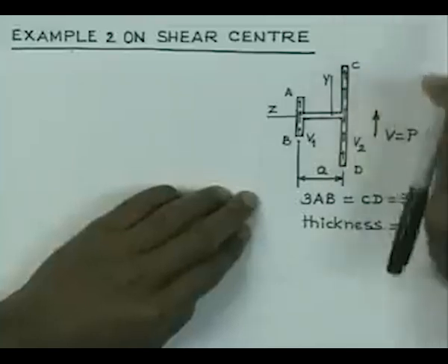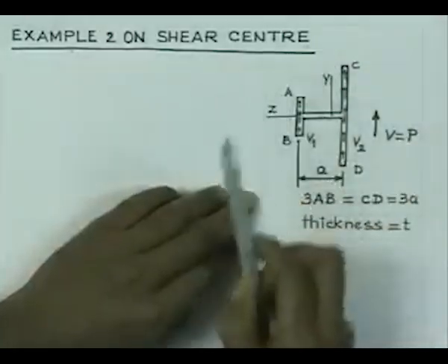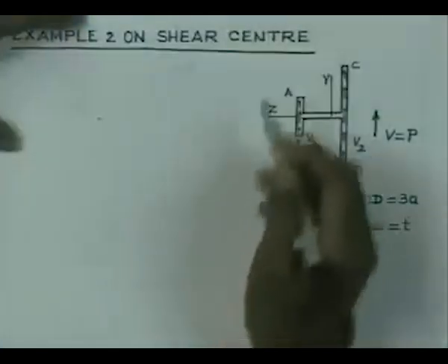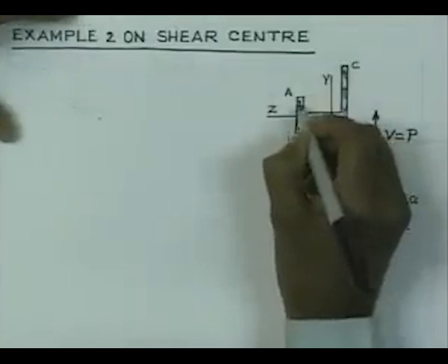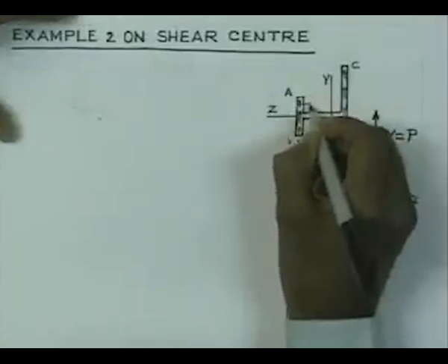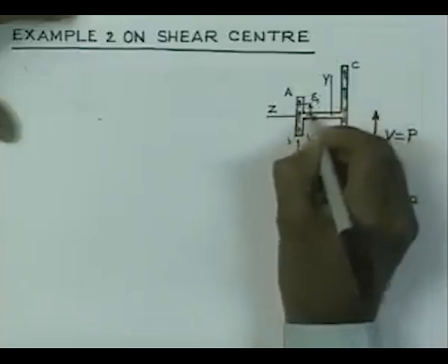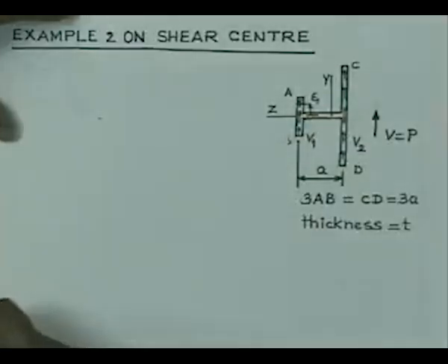So, the plane of the loading must be offset with respect to y axis so as to remove the twisting of the cross section under bending load. So, in order to do that, let us now consider the force V1 coming up on this arm AB. So, we consider a section or fiber at a distance of, let us say, xi from the neutral fiber,